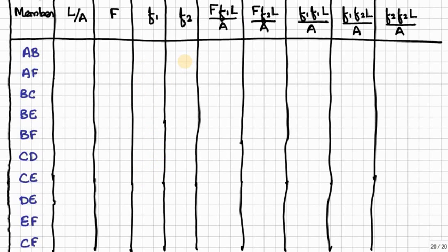For f2, we remove all the loads. Now we have only the primary structure. On the primary structure, we will apply a unit load at the second redundant force. Now we will find the force in each member using the method of joints again. Then we will list all those forces here.